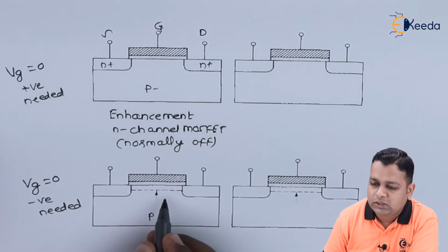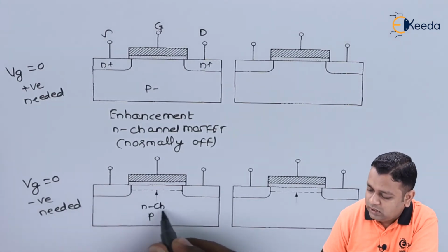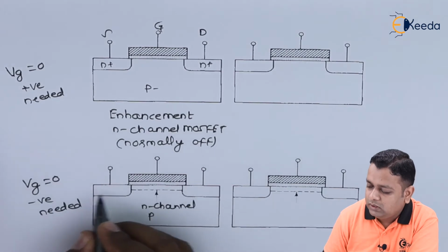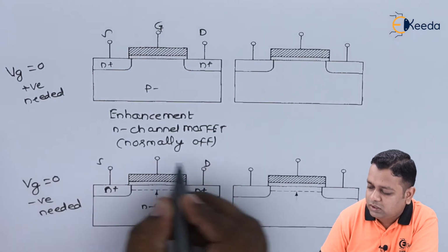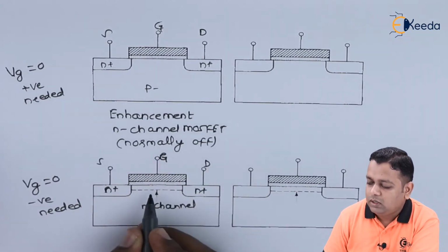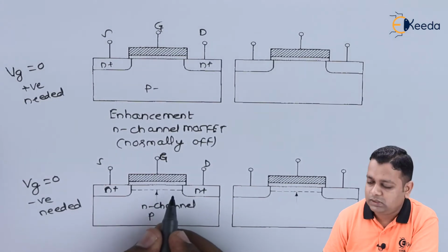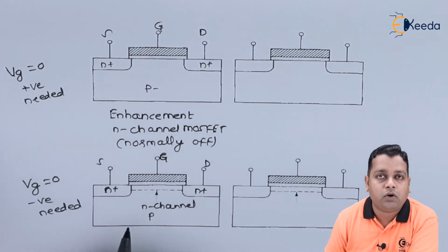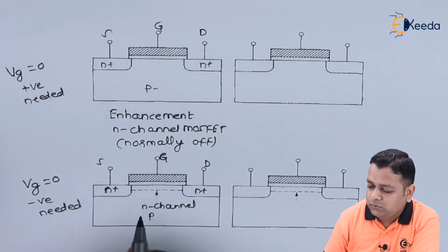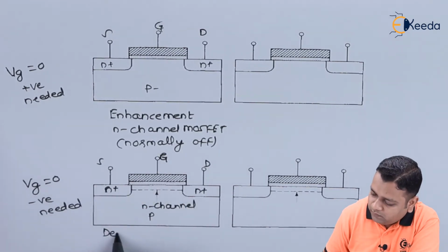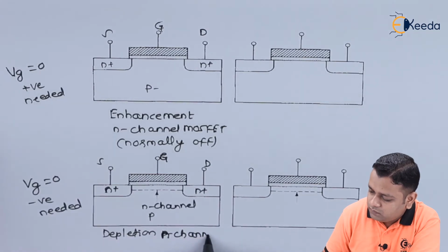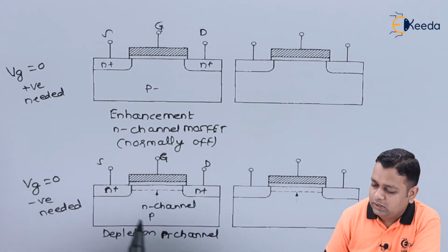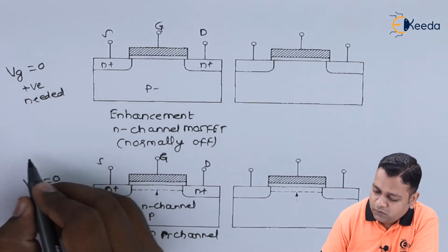so that into the channel here, so this is the n channel, the initial structure is the same here, this is n positive, this is n positive corresponding to the source and drain, and this is for the gate. There it will be the depletion inside the n channel here. Hence this type of the n channel MOSFET is called as depletion type. So this is the depletion type. Here it is n channel, and this one is normally on condition here. So I just mentioned here,